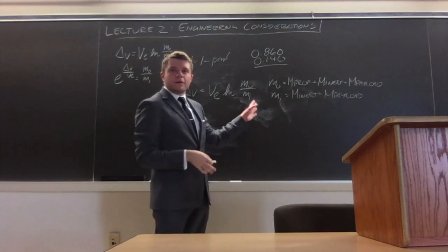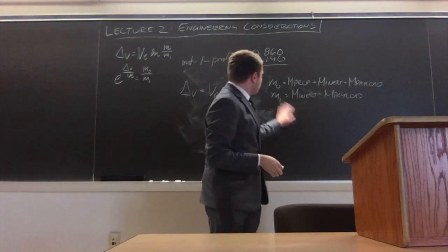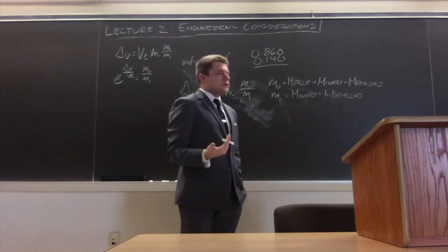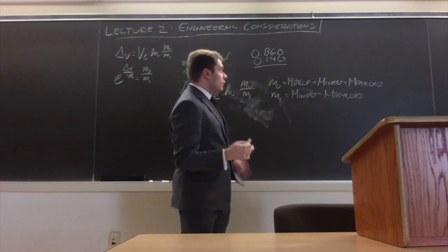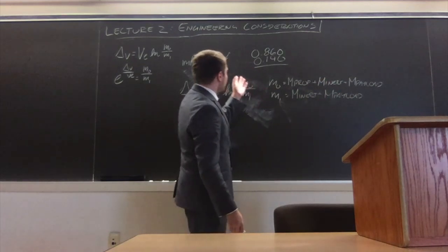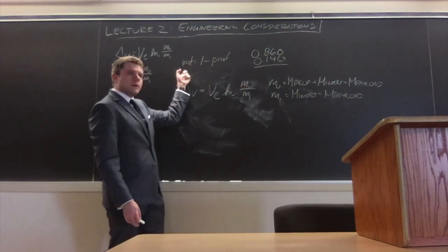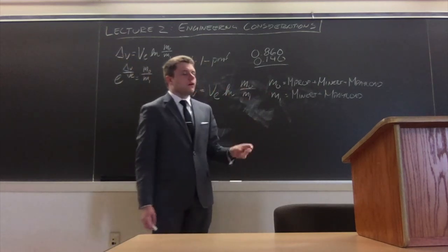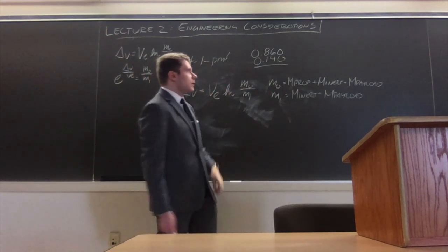Now, we can look at this in such a way that we can start to constrain these terms. Because these are all kind of unrelated, but we recognize that we have the propellant mass fraction and the inert mass fraction of the stage available to us. So we can actually define two of these terms with respect to the same term.